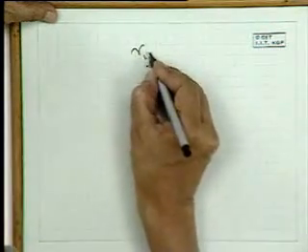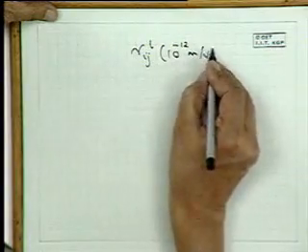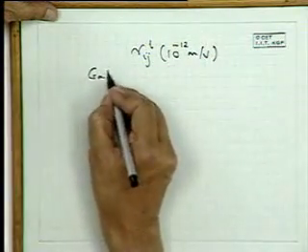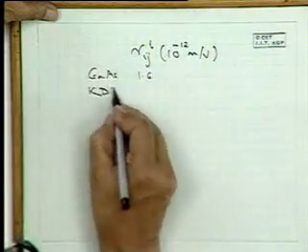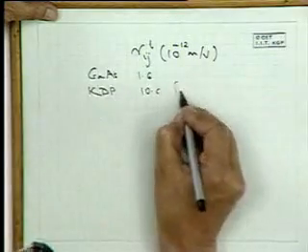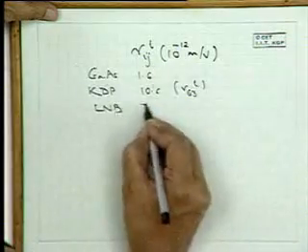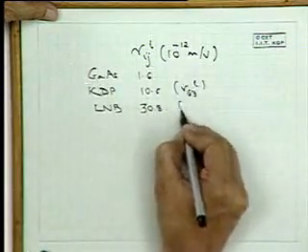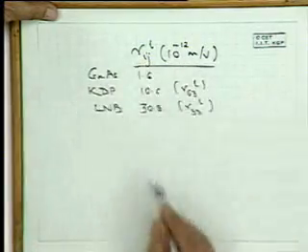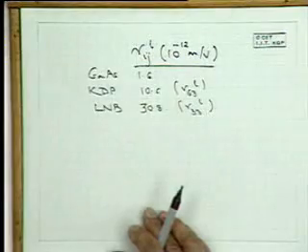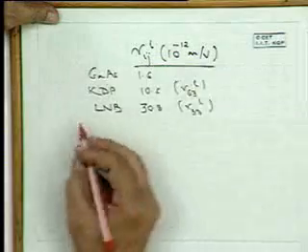This is a bit of a repetition. r_ij in 10 to the power minus 12 meters per volt: for gallium arsenide, this is 1.6. For KDP, values are much larger, 10.6 for r63, and for lithium niobate, this is 30.8 for r33. Okay, these are conventional bulk Pockels coefficients. Now what happens when we grow quantum wells?